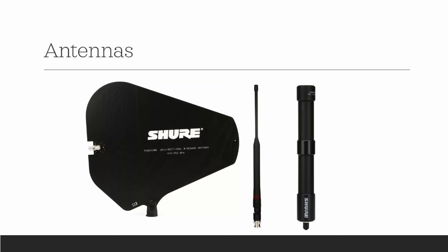Just like you think about polarized sunglasses and a screen like your cell phone: you turn your screen 90 degrees and the screen looks black through your sunglasses. Exact same concept here with your antenna. Because they're polarized, if you go 90 degrees out of orientation, they'll cancel out. Generally speaking, your polarity nulls are going to be about minus 10 to 12 dB. To put this into perspective, yes, losing 10 or 12 dB of signal is huge. You're definitely going to notice and create problems.